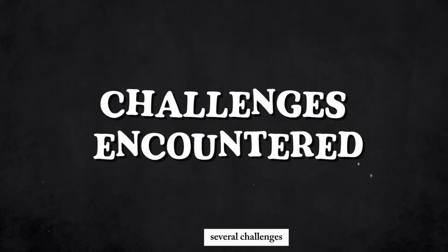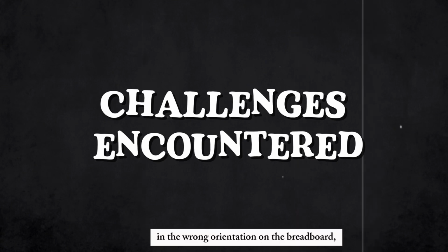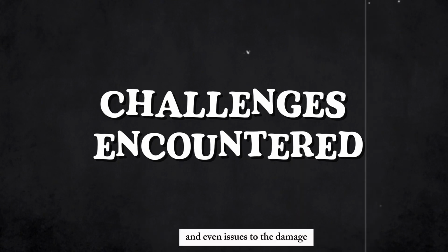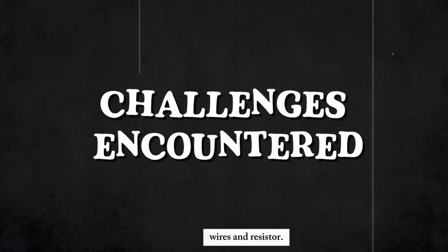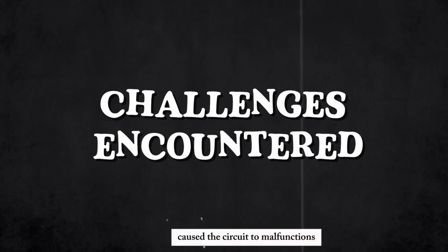We faced several challenges, such as wrong wiring connections, placing the display in the wrong orientation on the breadboard, coding errors, and even issues with damaged wires and resistors. These mistakes caused the circuit to malfunction and delayed our progress.